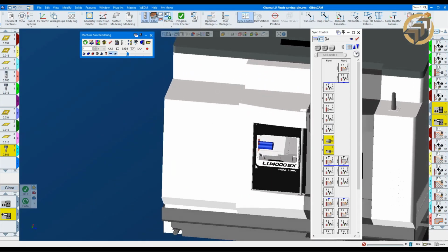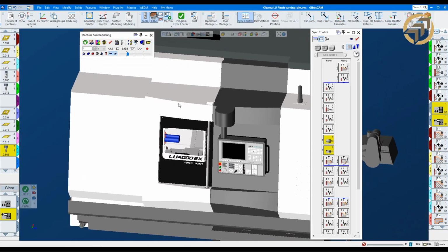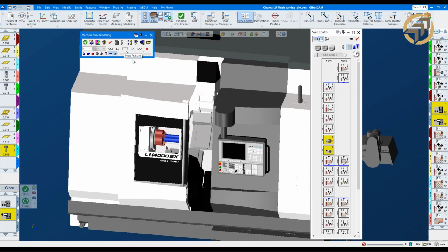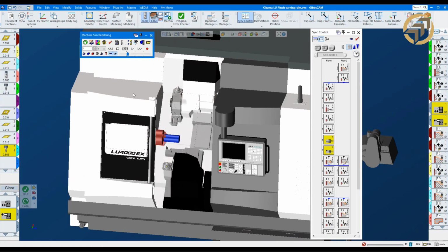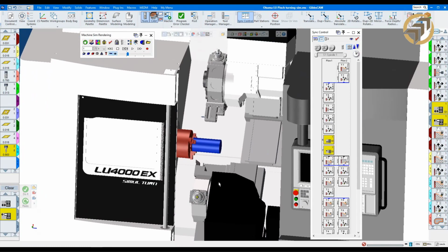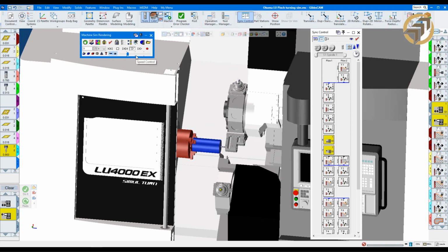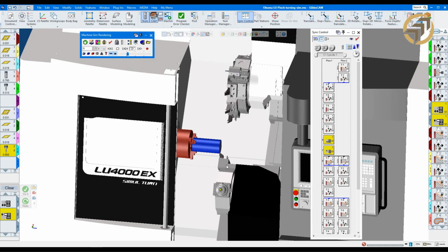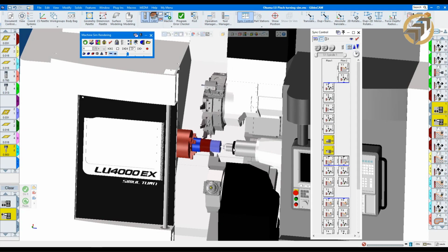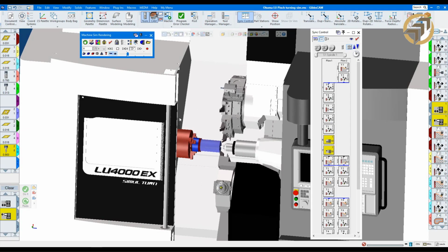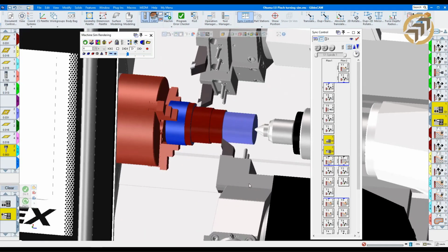Unzoom. And we have again a closer look at our machine simulation one more time. And then I'm going to go back and tell you how I can synchronize things up. Again, the lower turret was waiting until the upper turret is ready and the tailstock is in, so they can machine together for our pinch turning operation.